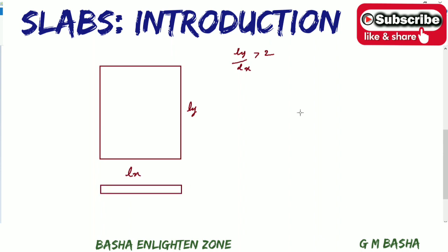There will be deformation like this in the one way slab, means it will be deformed along the shorter span. One way slab bends in one direction, that is the shorter span direction, and that is the reason the main reinforcement is required along the shorter span direction to resist this bending and deflection. So we need reinforcement along the shorter span direction only, and we have to provide the distribution reinforcement in the longer span direction.